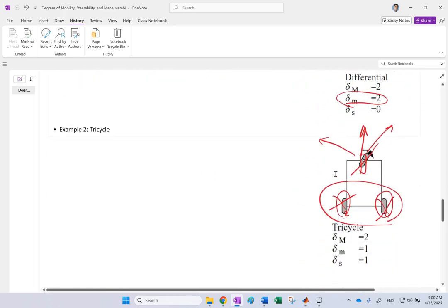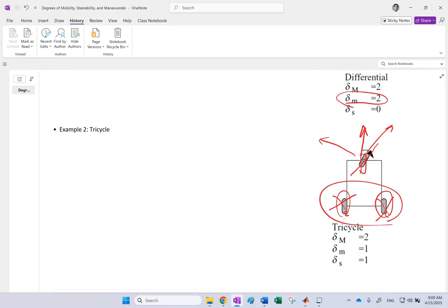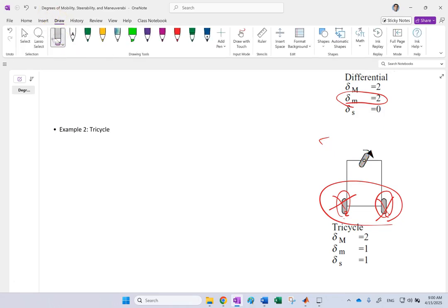Because rank will tell you whether these steerings are basically giving you anything independent from each other or they're all the same. For instance, if I go here and I add another one just like this here, and I sync these two together, so when one spins, the other one spins with it too, I can say, hey, look, there are two steerable wheels here, right?